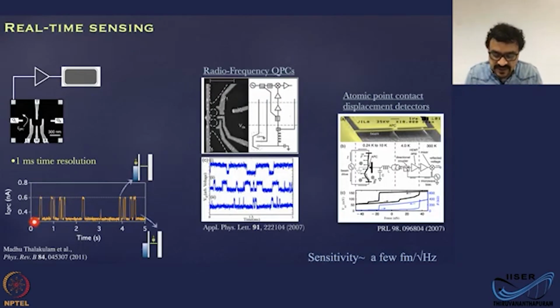So here we can measure the change in the current through the QPC as a function of time, and you can get the fraction of time the electron has stayed in, and what fraction it has stayed out. Because when the electron is inside the dot, the QPC is going to feel a more negative or lower voltage on the gate. That is how the effect is getting translated. So you will measure a lower current level. When the electron is outside, it's a less negative field or lower energy, and the current will go up.